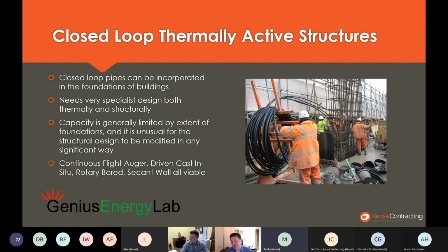And on some of the systems that I've worked on a lot, the piles form like a base load, a core energy recovery system, and then we've got something else going on like water wells, for example, to then take the peaks out of it. That can be a very effective method. They're really good at energy recovery, particularly in London, where they're surrounded by London clay, which is quite dense, quite low conductivity, but quite high specific heat capacity. So it's a really good store of energy.